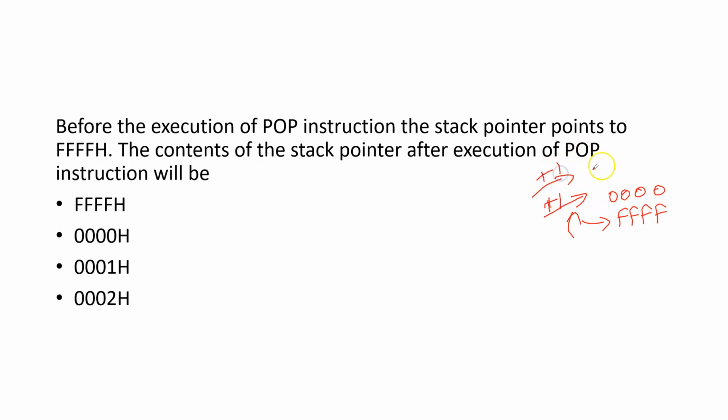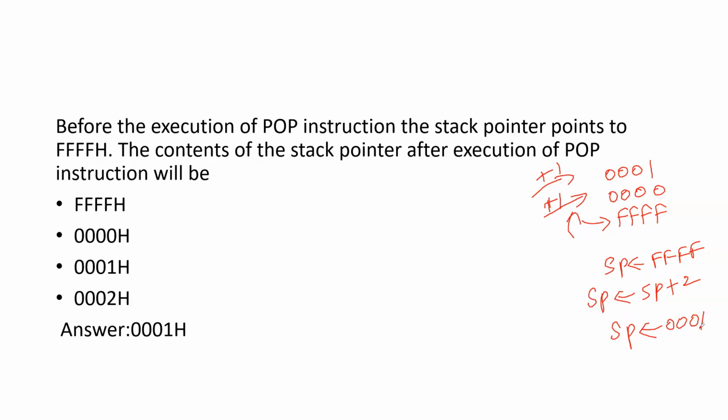Again one more increment will be there, so this value will become 1. The stack pointer was previously FFFF. Now because of the pop operation, the stack pointer becomes SP plus 2. So now the value becomes 0001. So the answer is the third option, 0001.